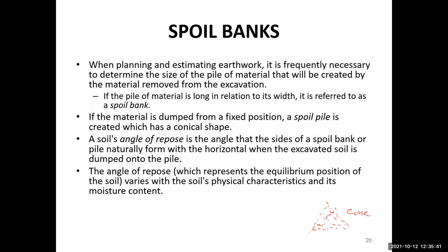A spoil's angle of repose is the angle that the sides of the spoil bank or pile naturally form with the horizontal when the excavated soil is dumped onto the pile. So for example, if the soil is being dumped into this pile, the truck comes from here and dumps the soil over here, the soil will stand in its natural condition at some angle.